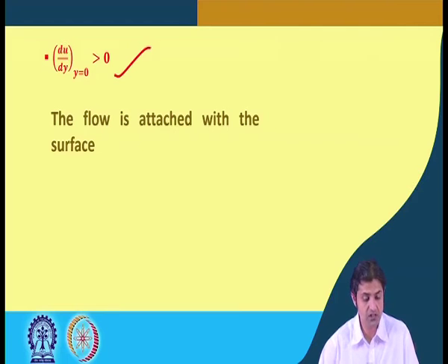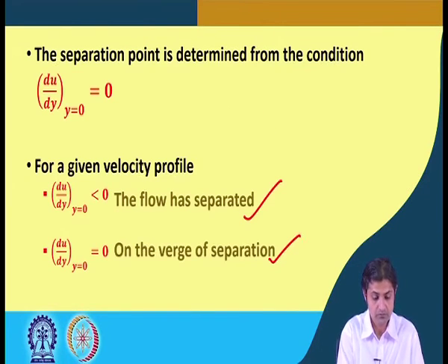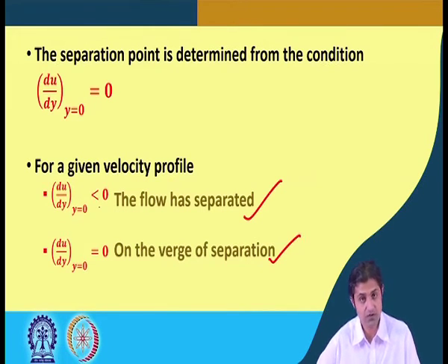Because du/dy at y equal to 0 gives the shear stress, that is the main thing. If it is less than 0, that means flow has already separated.